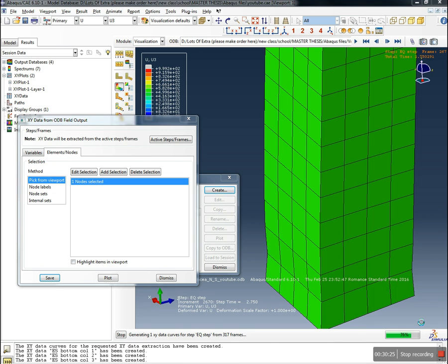You have to check what stresses you have there, and design the stirrups. Again, we are not using design here, so I just know based on experience as well that I have seen a lot of tall structures in seismic areas that have the first story higher than the other stories. And it's typical for buildings that have shopping centers at the ground floor, and just apartment buildings for the rest. Or at least this is what I observed, as I said in previous observation just around the city.